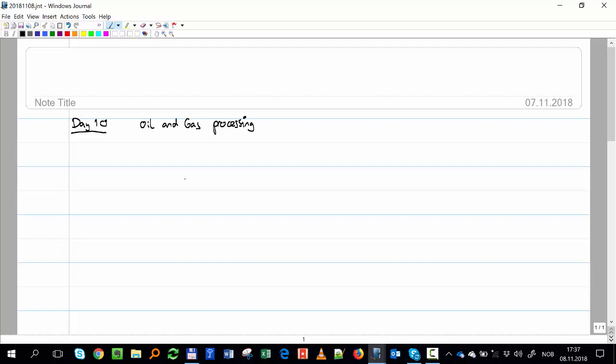So far, we are saying we have our well, and we are producing to a separator, and that's it. And somehow magically, we get our oil and we get our gas. But in reality, it's a very complex process that has a lot of parts. But the reason why we can just use one single point here and don't look at anything else that is downstream is because here we have a fixed pressure. We have a boundary with constant pressure. That's why we can take all the rest out of the picture.